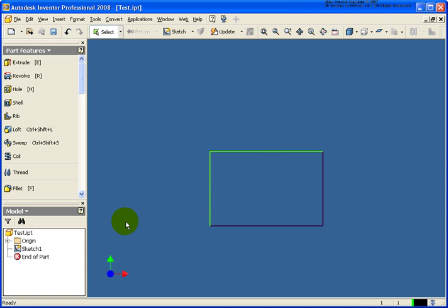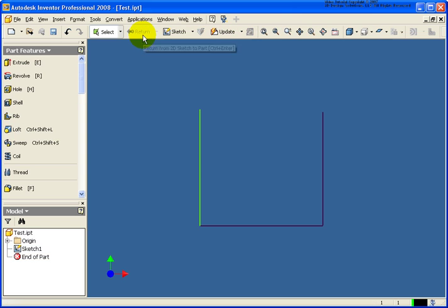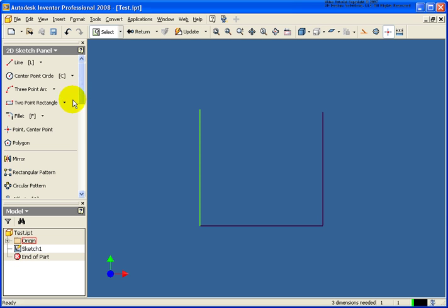Now there are 2 ways of doing that. I can click on the Sketch tool, then click on some geometry in the graphics window, or click on Sketch 1 in the browser. You'll notice all of my tools are available here. I can grab one of those lines, erase it, drag and pull whatever else we need to do. So let's do this one other way. I'm going to click Return. That will also exit me out of that sketch environment. I can also just simply double click on Sketch 1 in the browser to make that active.